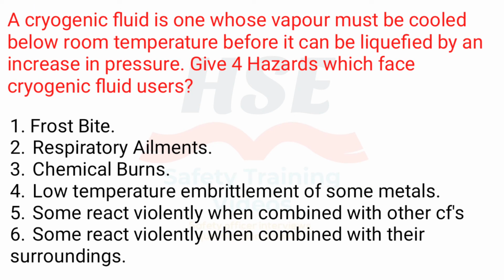A cryogenic fluid is one whose vapor must be cooled below room temperature before it can be liquefied by an increase in pressure. Give 4 hazards which face cryogenic fluid users. 1. Frostbite. 2. Respiratory ailments. 3. Chemical burns. 4. Low temperature embrittlement of some metals. 5. Some react violently when combined with other cryogenic fluids. 6. Some react violently when combined with their surroundings.